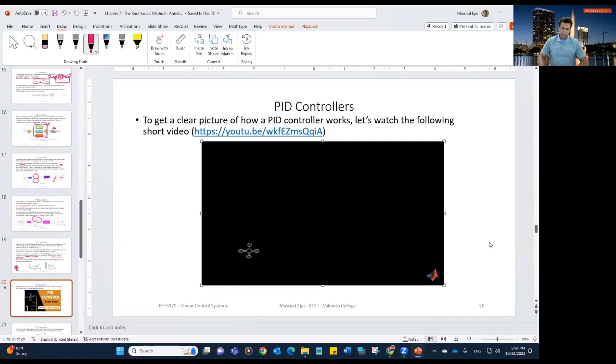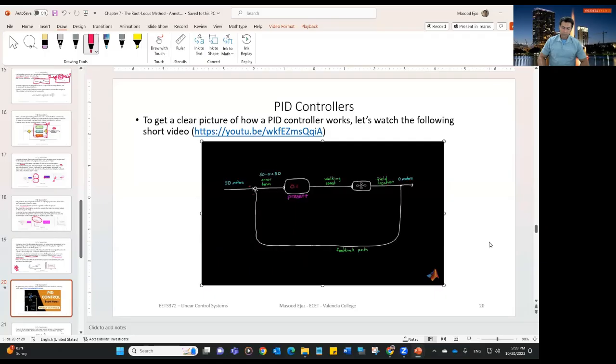In this second example, you want to design an altitude controller for a quadcopter drone. The drone has 4 propellers, and when they all spin up together, they produce a force that lifts the drone up into the air. This is similar to our walking example in that we're trying to get to a specific location, but this time we want to get our system to hover at an altitude of 50 meters. Our plant is the drone, and the output of this system is altitude. Now, the input of the system is not walking speed, but propeller speed. And all in all, it seems like a pretty similar problem. So how well does a proportional controller work in this case?